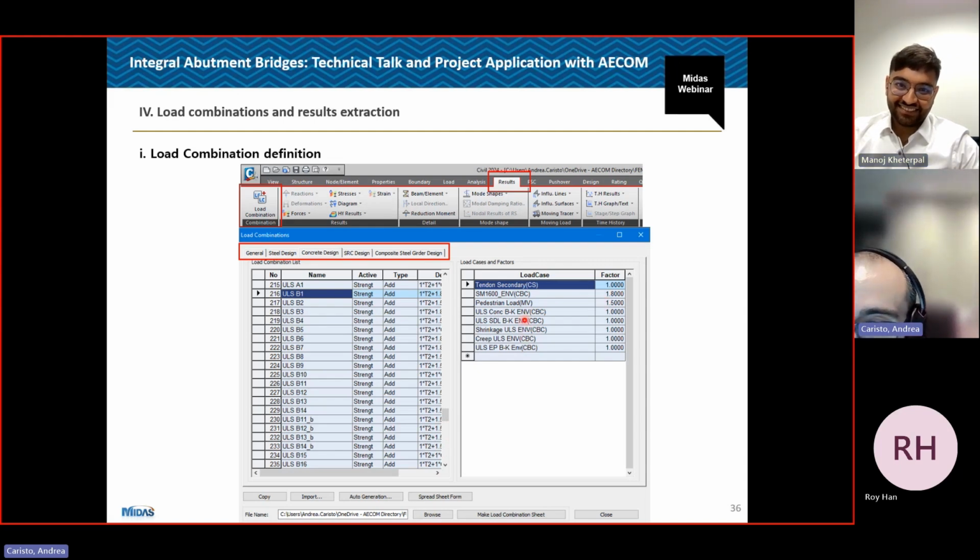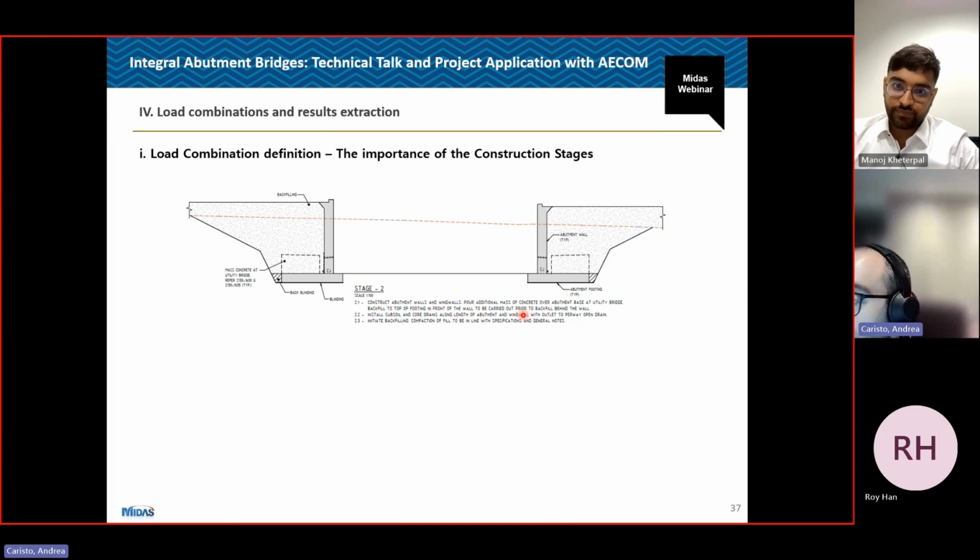One thing I want your attention on, you see this tendon secondary as a CS there, okay? Normal static load cases, apologies, will have ST on it. I want to just spend 2 minutes on it because it's really important that you understand the difference between these because it can bring really big problems. So the importance of the construction staged analysis cannot be underestimated.